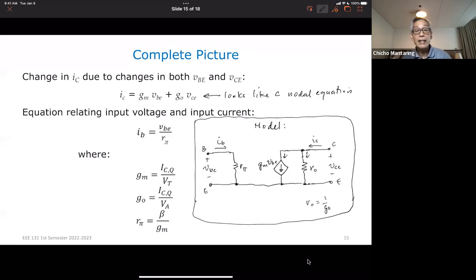Okay. So this is now my model. This is what my transistor is equivalent to. This is just the transistor, with no resistance attached, nothing, just the transistor by itself. If we're doing small signal analysis, that is, if we're only considering small variations in the input signal, and if it is properly biased, that is, biased in the forward active region at an appropriate bias point, then we can use this model to compute for voltages and currents, as long as the variations in the input voltage are very small.